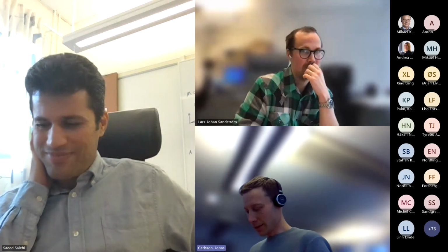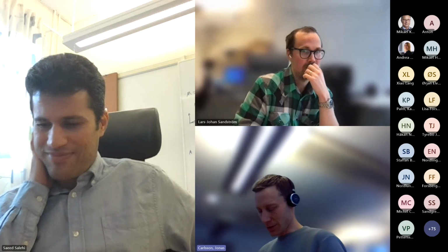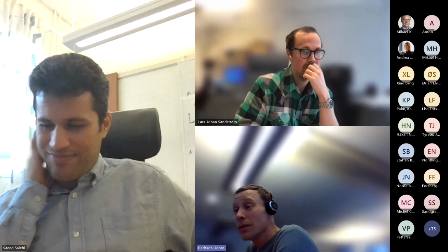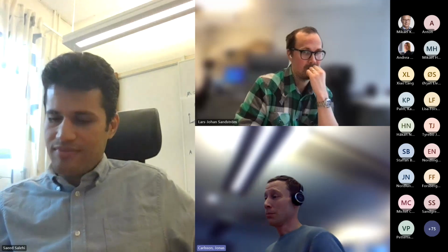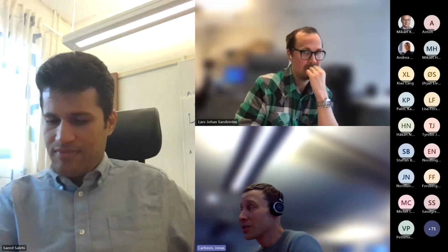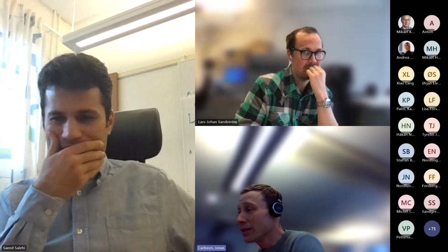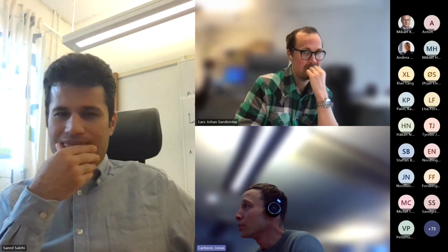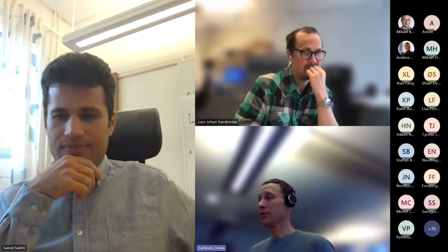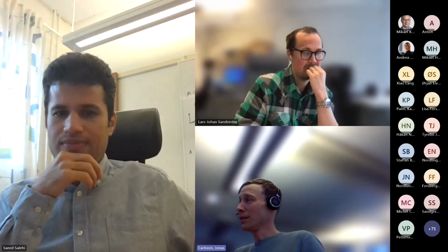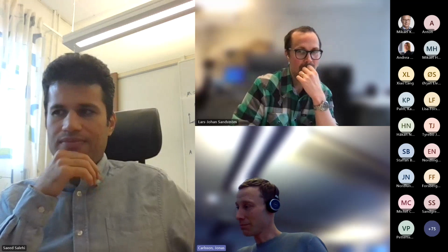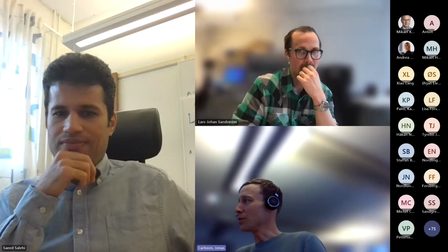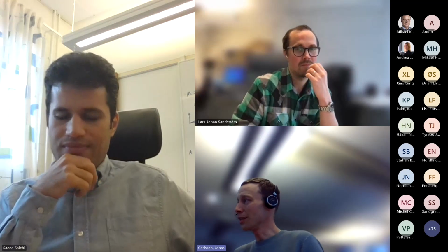All right. Yeah, that's kind of interesting, because we have some units today where, at some loads, we can actually hear the vortex rope pounding in the draft tube. It's just in specific load regimes.